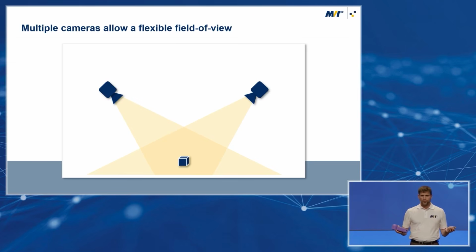So we could just use a much wider baseline. Even we recommend it. In this case, we are much more distant, and we have a very different perspective to the object. This gives us accuracy and less false positive detection. But for the reconstruction, this setup wouldn't be very good. So we do not have this compromise. We can add the camera where we want. So in this case, both cameras, we have the field of view, one object.